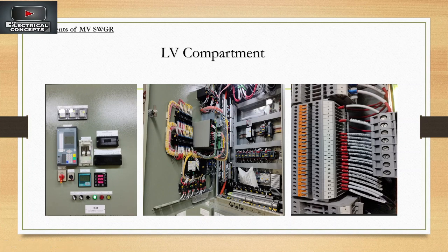You can see how these components are connected through control cables and through fiber optic cables. The orange fiber optic cables are the communication cables connecting the relay with the control system, the SAS, substation automation system. This is the terminal block where the wires are connected through lugs and ferrules. These white labels are called ferrules, which are printed at the manufacturer facility for internal wiring.